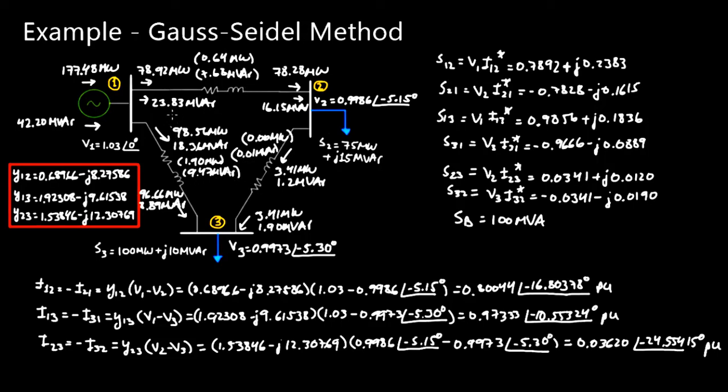So you can see how these power flow analyses are very complex, and if you do them by hand it would take forever to perform. This example, for example, took us about an hour to solve, and it's a fairly simple system. I mean, we only have 3 buses and 3 transmission lines and 1 slack bus. We didn't even have another generator in the system. And so this can get very, very complex very quickly, and it becomes really inefficient to do by hand.